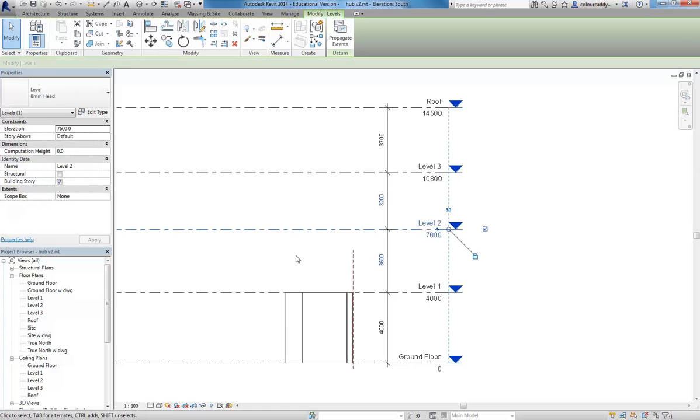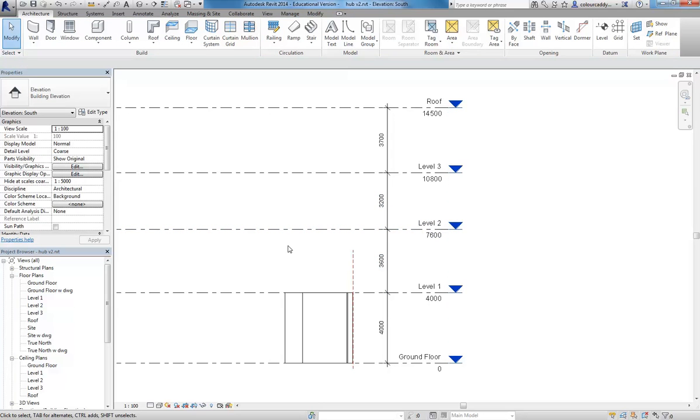Sure. So if you have 4 levels, and if you have a building, which is the facade of the building connecting from ground floor to the top floor, so you should show one wall. Yes, that's a really good point. Yep, that's what I'm going to show you now. You can try and have it as one continuous wall, but say if it's different materials or if it's just too awkward, if it is a different shape slightly on the next level, then it's sometimes better to stack the walls on top of each other. But only sometimes. Generally, if you can have one wall continuing through across the levels, that's the way to do it.